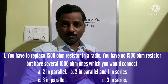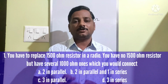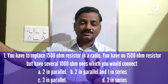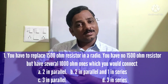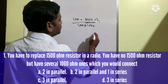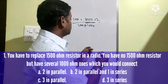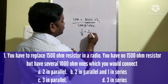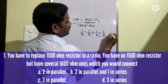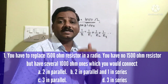If I have 1000 ohm and I take 2000 ohm resistors connected in parallel, its value will be less than 1000. If I increase that number, if I take 3 resistances in parallel, then again the value will be less than the 2 parallel resistance. If you simplify this, we get something like 500 here. If you connect 3 resistances in parallel, you can simplify it like this: 1 by R is equal to 1 by R1 plus 1 by R2 plus 1 by R3, and so on. So when the number of resistances in parallel increases, the total resistance will decrease.